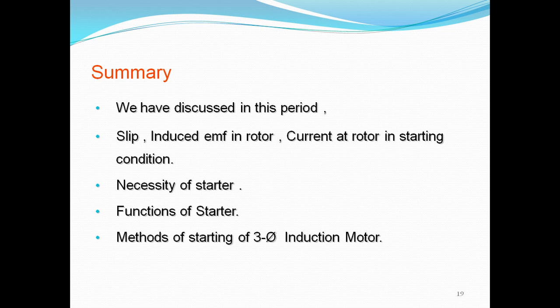And the fourth one is rotor resistance starter, where we will add some external resistance in series with the rotor winding. That is possible in slip ring motor only. As the motor picks up speed, automatically the external resistance is disconnected from the supply. So this method is used for starting the motor.